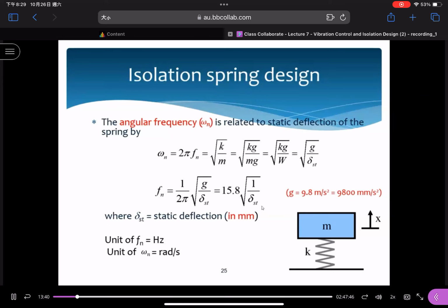How about if damping is equal to 0? If zeta is equal to 0, it means that C must be equal to 0. If C is equal to 0, that means no damping effect. So any problem about these two parameters, zeta and the critical damping constant? We set this critical damping constant because we need a standard line to compare the damping effects. We have 3 different cases.